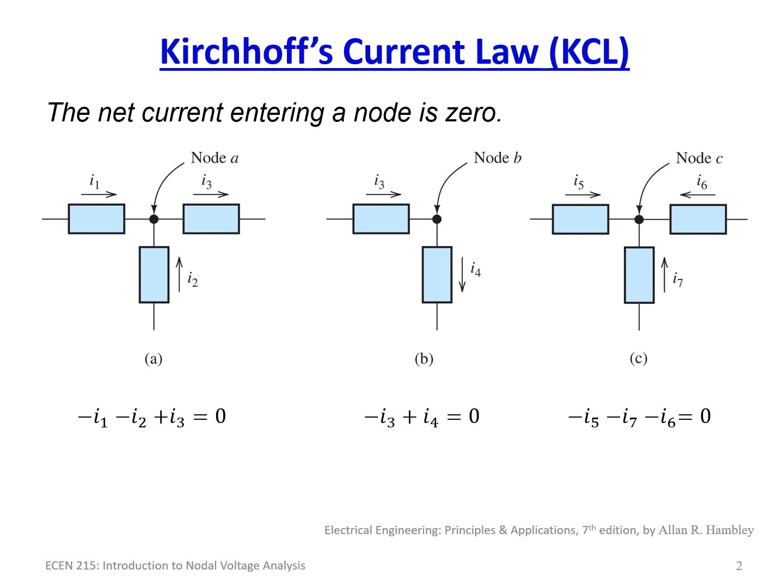And what this, and you're going to hear me say this over and over again, is you either choose entering as positive or negative. You choose what it means. In this, I always use leaving a node. It's always very easy to do that. So if we have I3 is positive, and then therefore I1 and I2 must be negative.